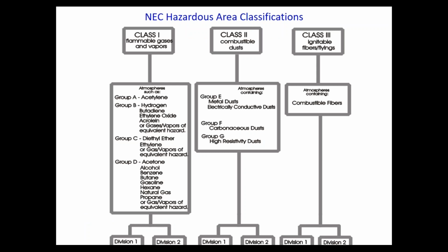When we spec out a gas detection system, we also get into the NEC hazardous area classification codes. For combustible gases, we're really talking about a Class 1 for flammable gases and vapors. We do have some hazards from explosion and fires from dusts, but we don't have any product that detects dusts or powders or something to that effect. So we're basically Class 1.